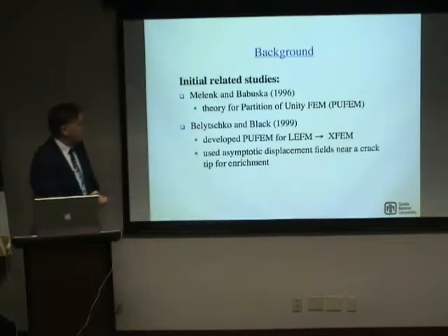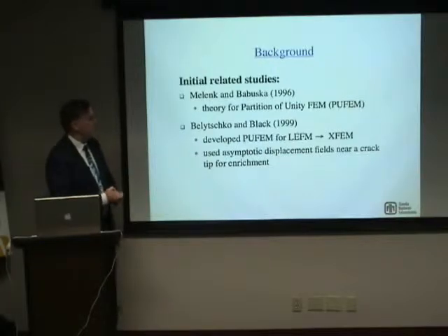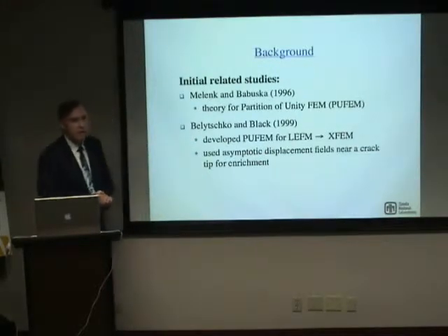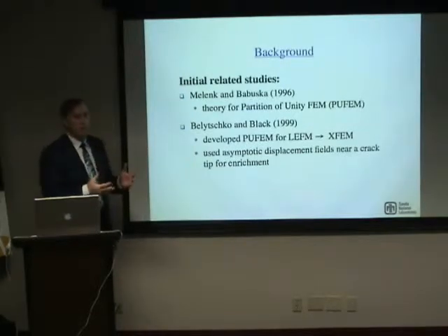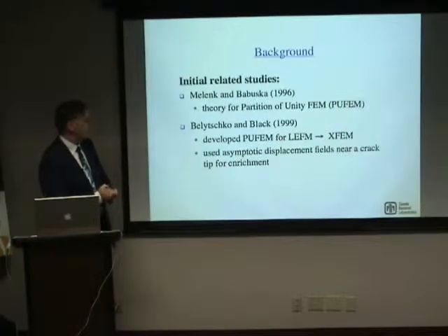Belytschko and Black in '99 took the ideas of the partition of unity finite element method and extended it for linear elastic fracture mechanics, and they used the term extended finite element method. The main distinction between that and PUFEM is that in using the functions that we do for linear elastic fracture mechanics, we're not just enriching the field, but we're actually introducing a geometry change, because these functions have a discontinuity in them. So that's one of the key differences.